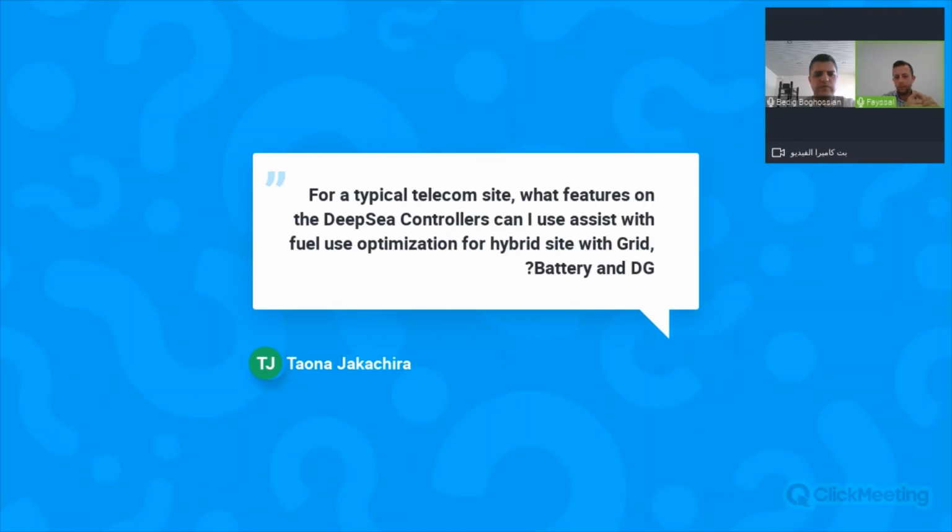Can I make a few comments? Oh, sorry. Yes, of course, for sure. About the surge protection. The surge protection has to be a separate device. It cannot be within the genset controller because they are totally different equipment. And regarding grid protection, our synchronizing controllers provide mains decoupling protections for rate of change of frequency and vector shift.